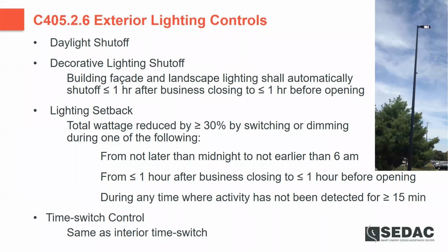So as far as this goes for exterior, as noted, we do have daylight shutoff that's required no matter where that is. For exterior lighting, whether that's general exterior lighting or facade and landscape lighting. And what we're trying to prevent here is what you see in that picture there, where here you've got exterior lighting on in the middle of the day. And in particular, LED fixtures are sensitive to temperatures. And so if we can prevent LEDs from operating in the middle of the day while the sun is shining, that's going to greatly increase their lifespan. So that can be very helpful there.